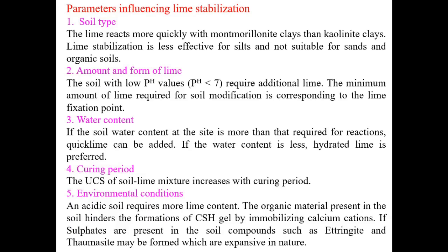Lime stabilization is less effective for silts and not suitable for sands and organic soils. The lime stabilization is not appropriate for sands because in sands the silica content is in the crystallized form. If a soil does not possess enough reactive silica or free silica, it can be supplemented in the form of volcanic ashes or fly ashes.